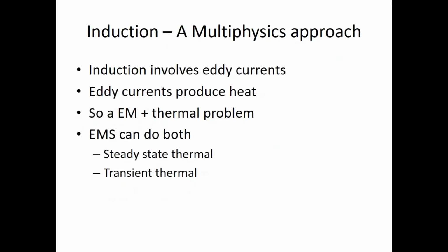Now, before we do that, induction is actually, as I mentioned here, a multiphysics approach, right? Why? Because induction, as the name implies, induces or produces what is known as eddy current or induced currents in the metallic structure, especially in metals, conductor materials, right? Now, this eddy current produces some kind of heat. Sometimes it's desirable, in the case of induction heating. Sometimes it is undesirable, in other applications where a time-varying magnetic field will produce heat, which is not desirable.